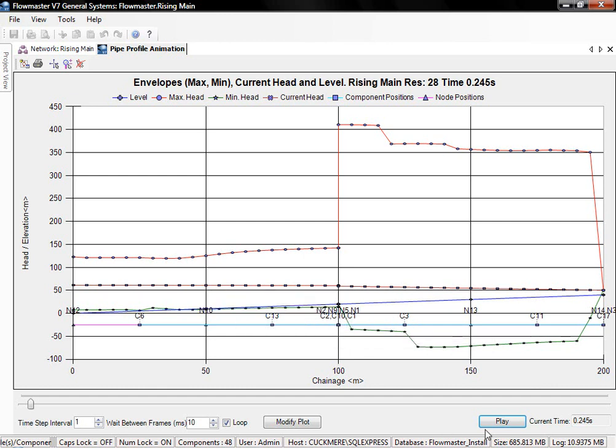Finally, we have this pink line, which initially, with both pumps running constantly and no change, remains roughly constant. But as we trip the pump first and then close the valve, we'll see that that line starts to move. And eventually, it will cover the entire range between the maximum and minimum pressures.